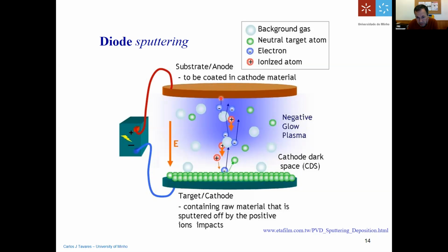And in between, you will have to put an inert gas, which can be ionized, for example, argon or xenon. And when the argon is ionized, you will have the electrons, which are necessary to continuously ionize the argon gas. You will have the neutral atoms, which are being sputtered. And you have some kind of residual gas, because even when you're working at 10 to the minus 6 millibar, you cannot say that you have complete vacuum, okay? Because you still have a residual gas, you still have some water vapor, you might have some carbon dioxide.